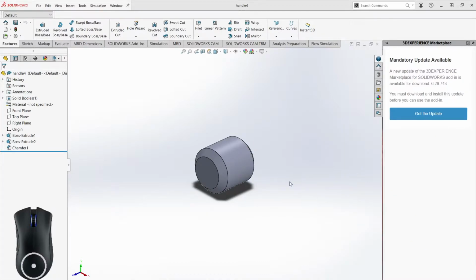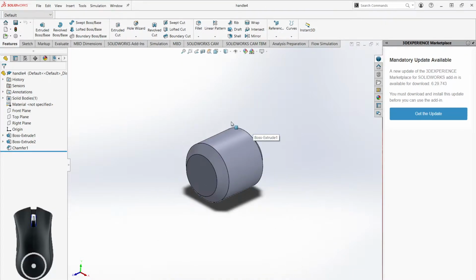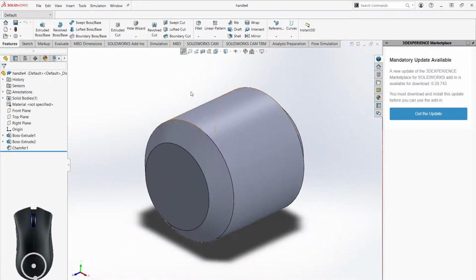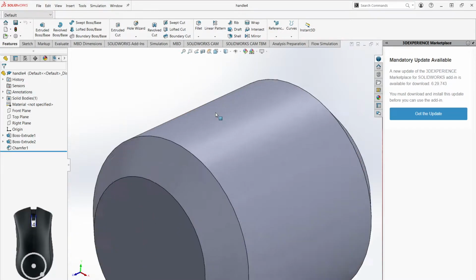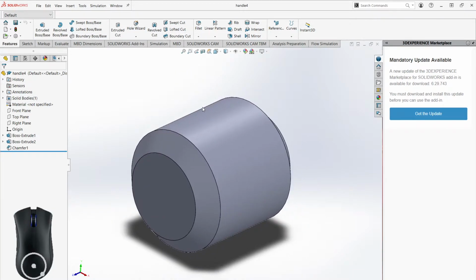Today we'll be talking about workspace orientation and just how to move around in SOLIDWORKS efficiently. So let's start with the toolbar, which is up here at the top, where my mouse is. And we're going to start with the zoom to fit tool. We can click the zoom to fit, and it'll just zoom into the part if we're farther away. If we're too close, it'll zoom out. You can also do this with the F key. It'll make the same adjustment.